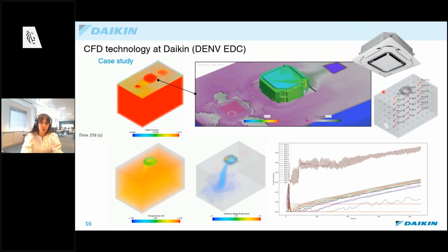During the simulation, we monitor several probes that are included in the room, which then makes it possible to compare to some test results. From those probes, we can measure the concentration of the refrigerant over time, how it changed during the simulation, but we can also see what is the overall behavior of the plume of leakage. This is something that, of course, from a test, is not visible.